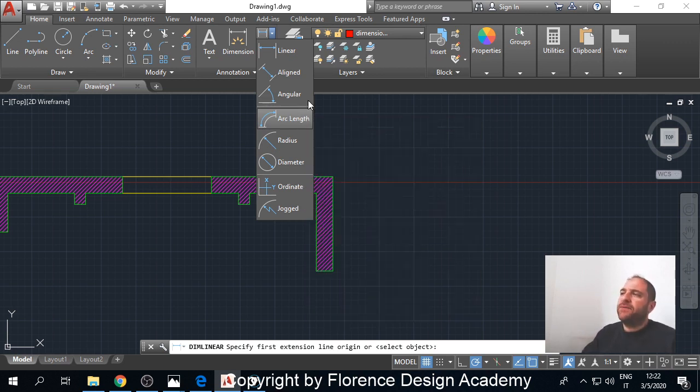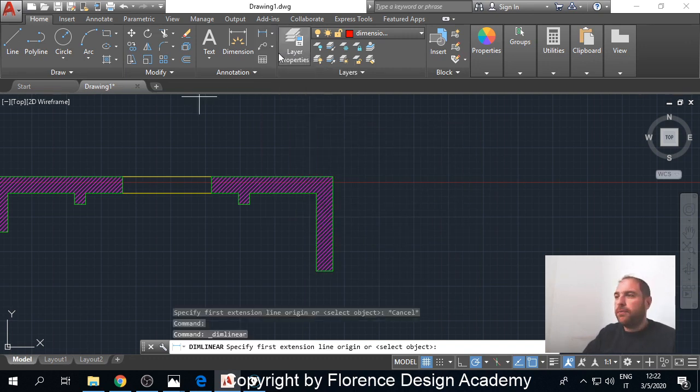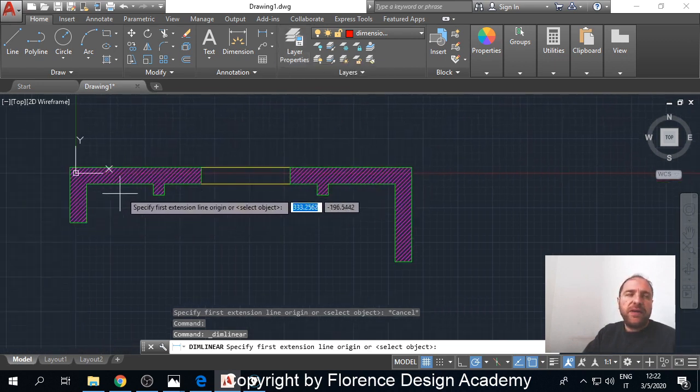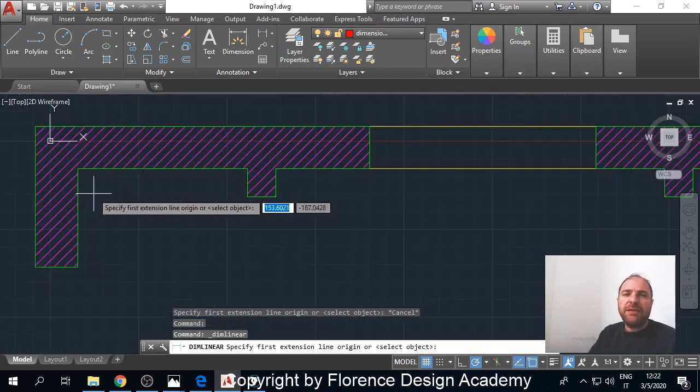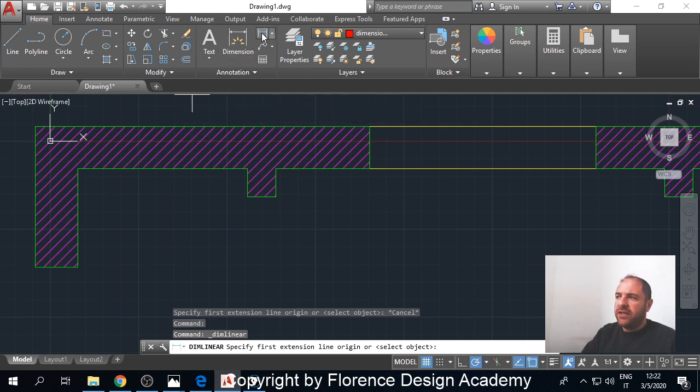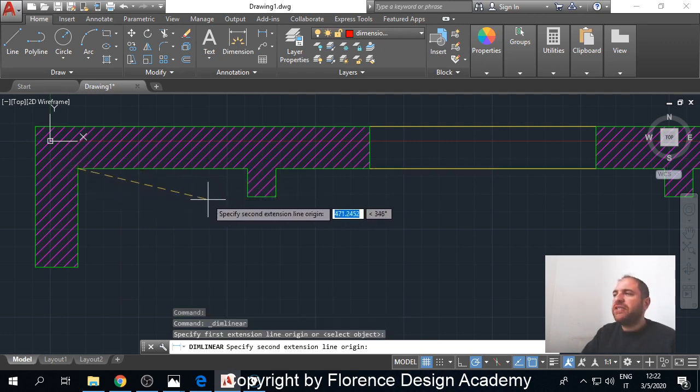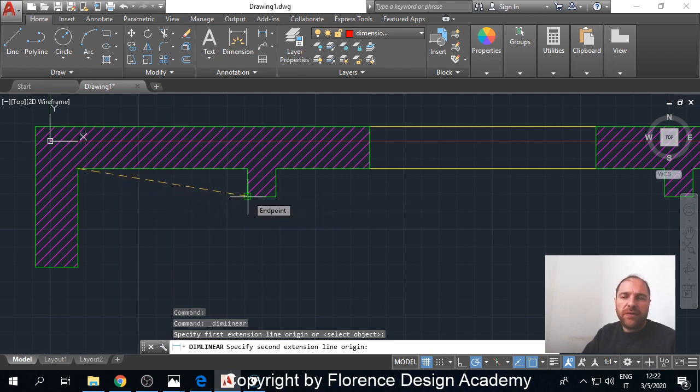The difference is this. When I click linear dimension, no matter which point I select, with dimension I will simply write the distance between 2 points, and it works like this. Look, you click linear dimension, then you click the first point, that is from where you want to measure, and then you click your second point.